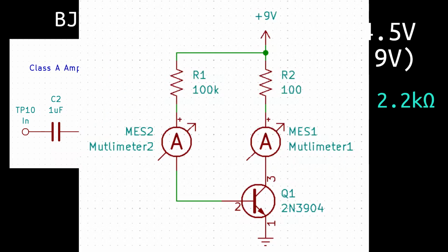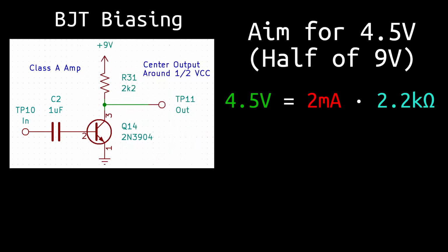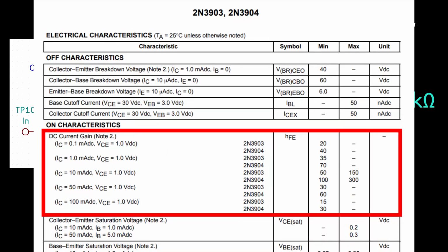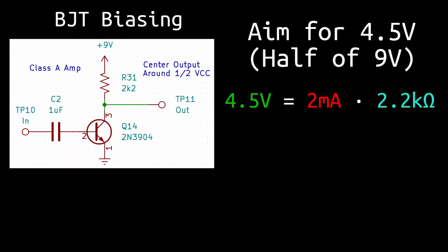We could try to do it like before, with a single base resistor to VCC and determine the current by using beta. This kind of works, but it isn't exactly the best in circuit design. You should know by now that the current gain isn't exactly the most stable figure, and it varies from transistor to transistor, different temperatures, and different currents. Rather, what we want to do is to set up the circuit such that it isn't dependent on beta.